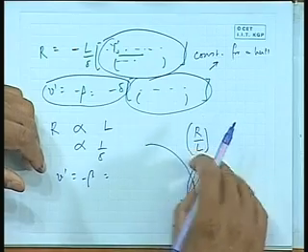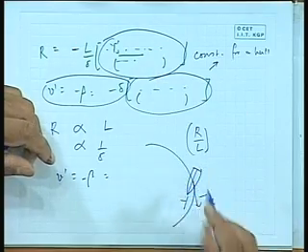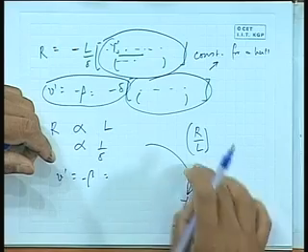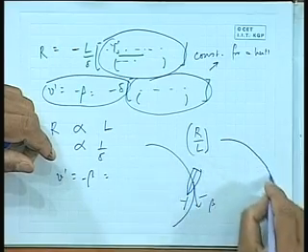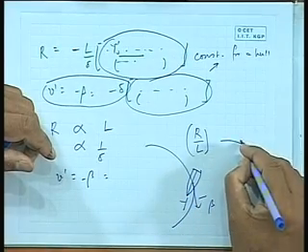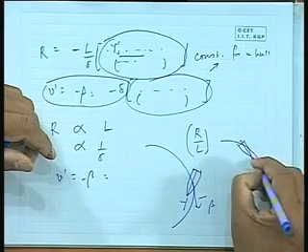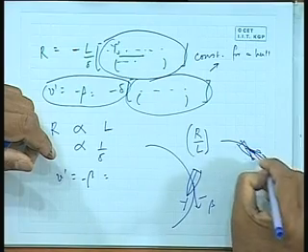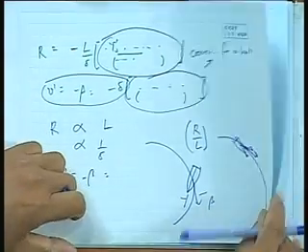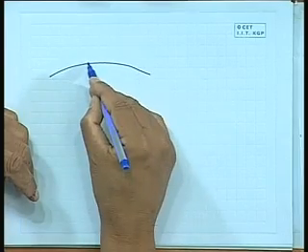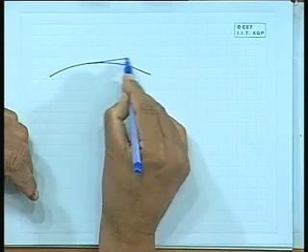If the rudder effectiveness is very strong, then it will have a very large drift angle and turn. If rudder effectiveness is smaller, then it will be like turning with a smaller angle. Or maybe another one I will draw. This is very interesting from the observation point of view. Let us see from this side turning. This is better maybe for me to draw also.